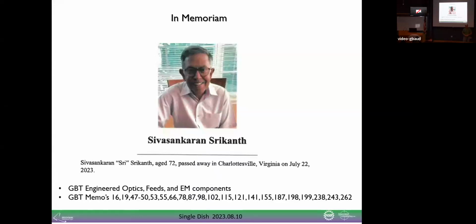Yes, sir. Is linear polarization your default configuration? Yeah, all the feeds are native linear. For the K-band, I don't know quite why they wanted circular polarization. It turns out if you cross correlate circular, you can measure linear. They were doing some measurements, and to get linear polarization you cross correlate circular. So the decision was to make K-band circular polarization, and that's where we put the phase shifter in there.